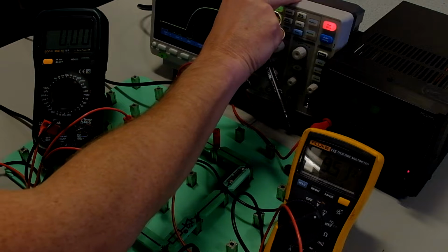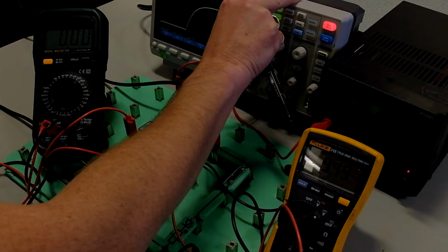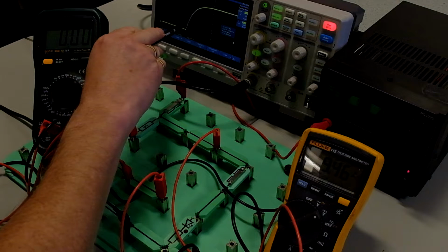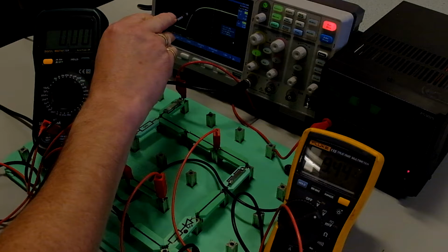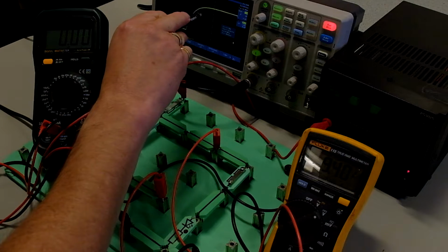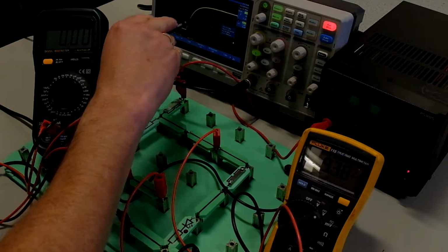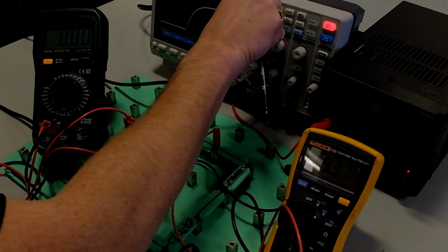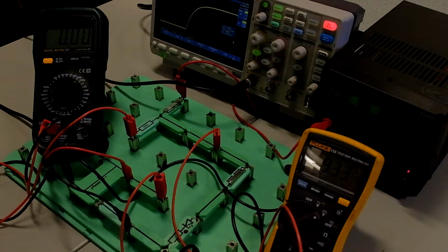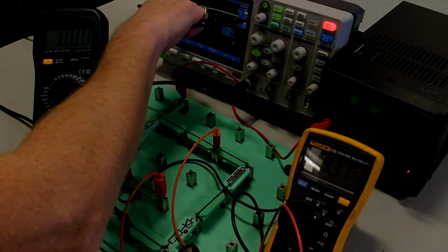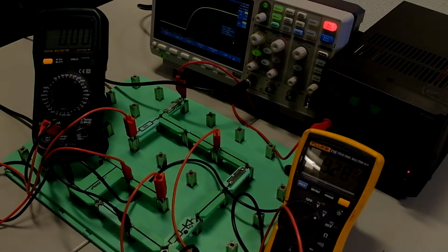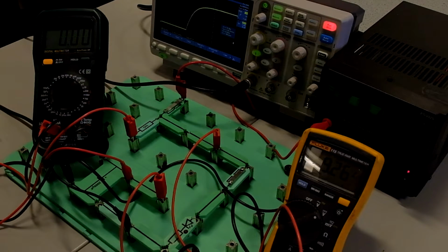How long is it taking to get up to 99% of 10 volts? So we're really talking about getting up to 10 volts. We can see that the rate of change of the voltage is very steep initially, and once it gets charged up, the rate of change slows down and it takes quite a long time to get to the full value. This is an exponential curve defined by Euler's number. It's not a straight line, it's not linear. If we look at that time difference there, we can confirm it does take 10 seconds to get up to the full 10 volts: 0, 2, 4, 6, 8, 10. So that does confirm by experiment it takes 5 time constants to get up to 99% of the supply voltage, which is 10 volts.